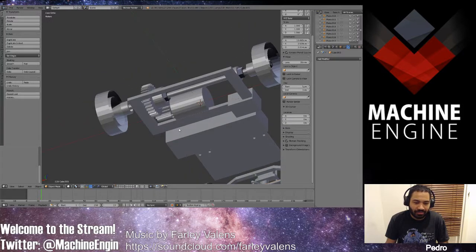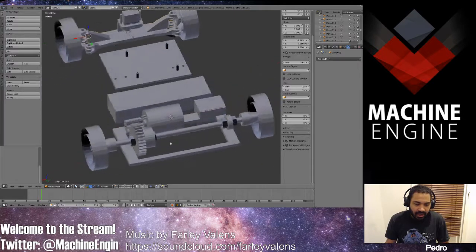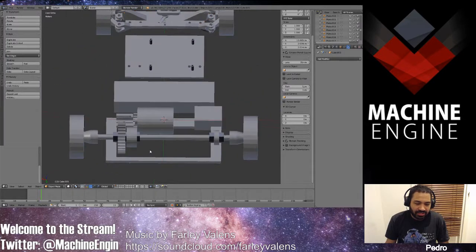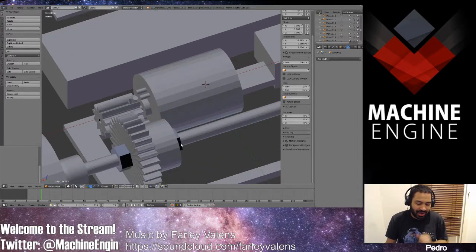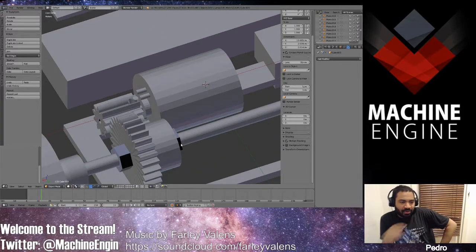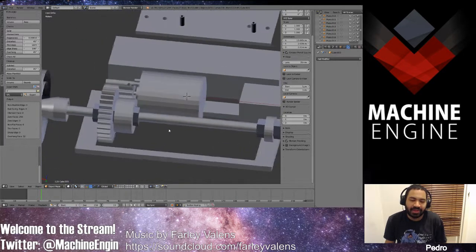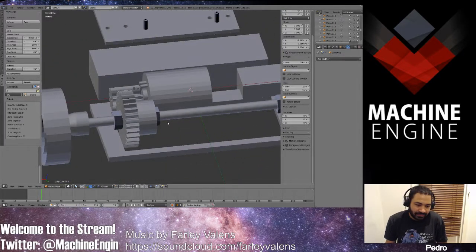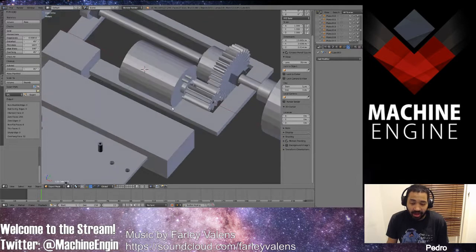Because if you have a bad mesh in games, you're gonna have issues. But with 3D printing, especially if you have the right software and the right printer, you can just go. The main things you have to worry about are non-manifold edges and bad continuous edges. Everything else, who cares? It doesn't really affect the print drastically or at all.